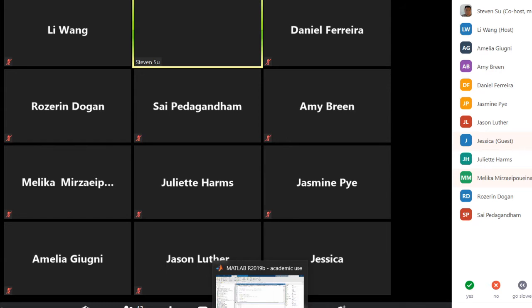You can try yours as well. We can have a competition to see who can generate the highest frequency. You swing your mobile phone to generate as fast as you can, and see what's the fastest frequency you can generate. In the future, if you measure frequencies over that frequency, you can just neglect them, filter them out, because that's noise, that's some error. This is a very interesting task, and one of the groups maybe can select that one.